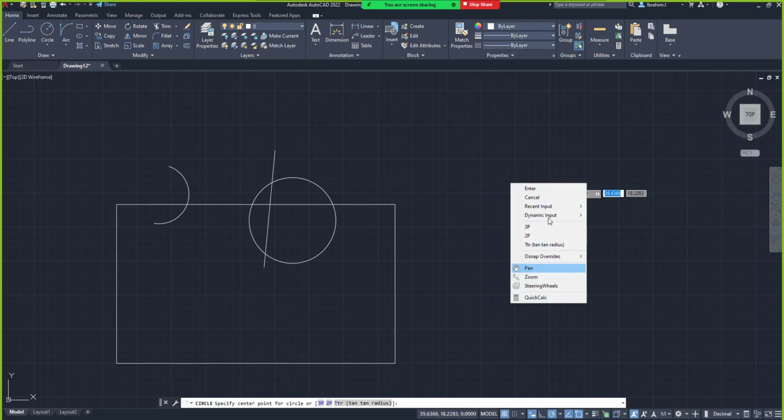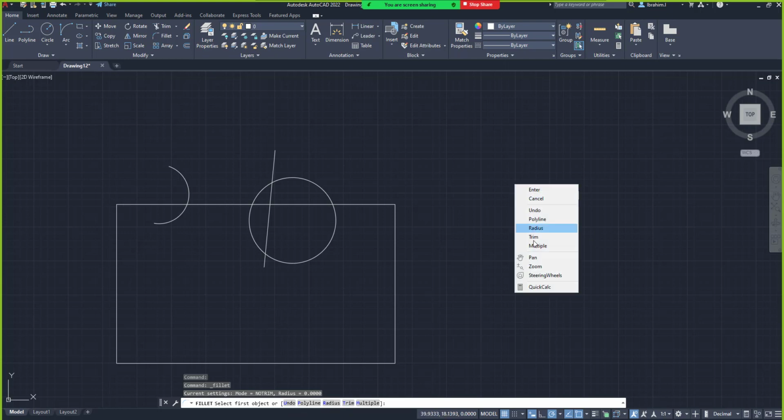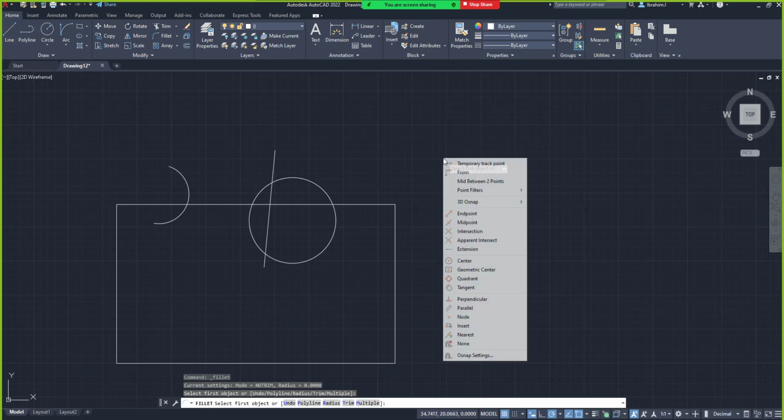can you see what it's showing me? When I right click by default, depending on the command you have, it shows you different options, for example to create a circle. The same thing if you have a fillet on; we have different methods of creating a fillet. But unlike just a right click, when you hold control, you have access to what? Object snap override. Can you see them here? They are the ones we have here.